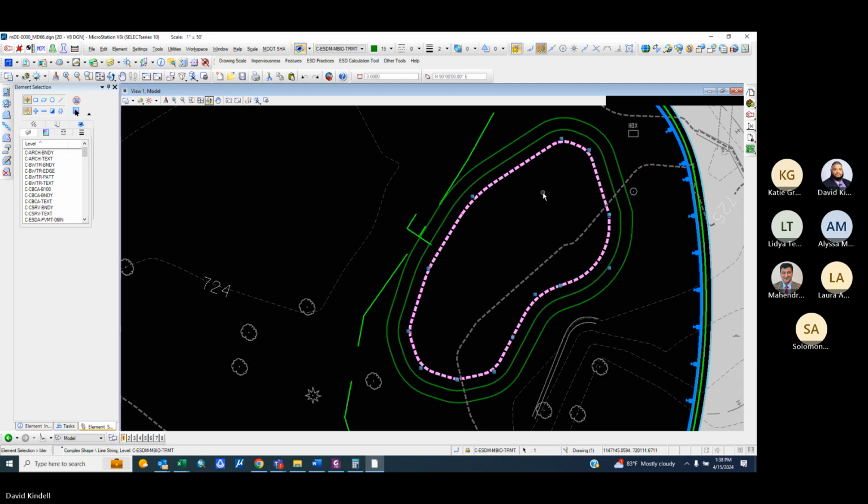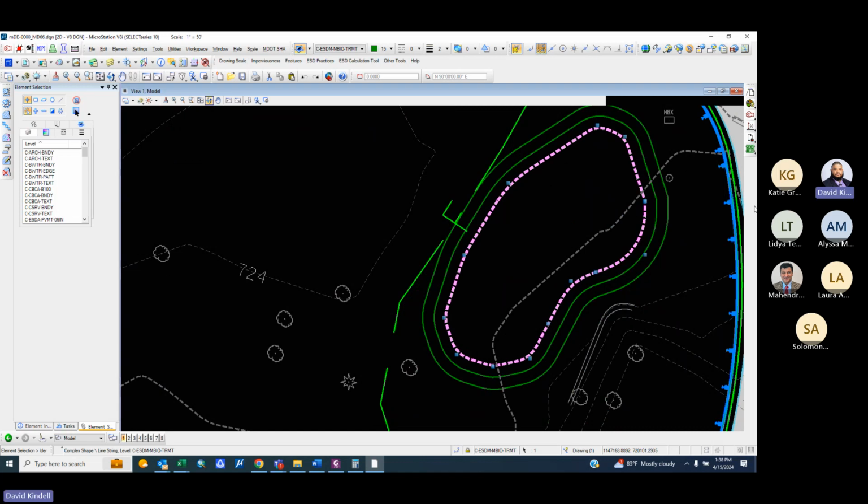But also, I feel like I need a berm here so I can have water flowing down. The other 723, 724. So I need a berm, at the same elevation. So I would make the 724, then I would make this 724.